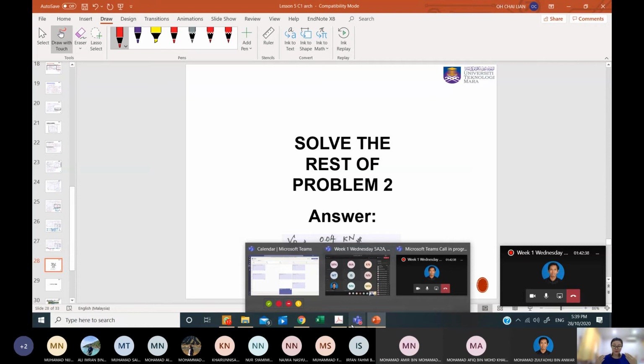If you still remember, for the truss we have nNL over AE. For the beams and frames or arch, it is actually the same: we will have M. What is the equation, class? Integration of small m, big M over EI dx, which was introduced to you last lesson.